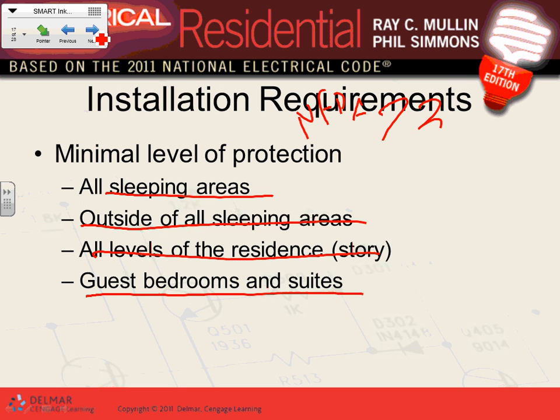In your building, we have four apartments. Each apartment is going to have one in every bedroom and one in the hallway in the front of it. Now, how about the common areas? In the common areas, guys, we end up putting one smoke detector in every common area, and we wire the common areas all together. Cool?